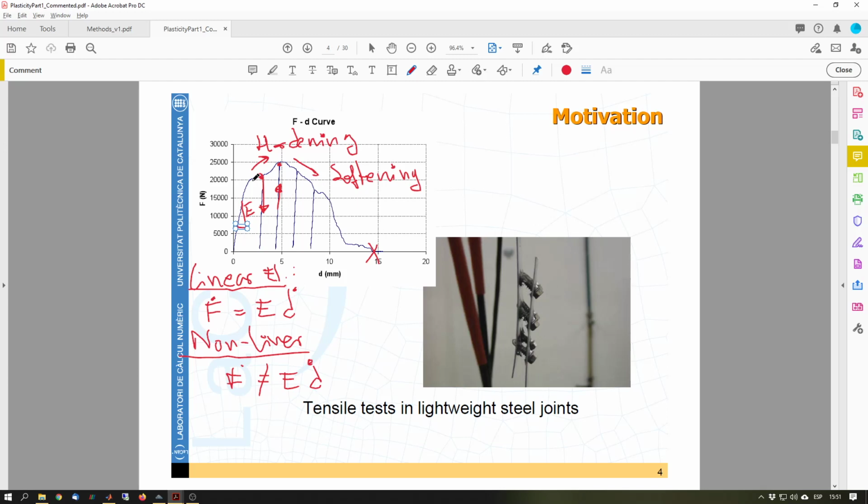So we are going to focus not on this whole history of loading and displacement, but on something more simplified, something like that. We are going to work on a simplified model to reproduce material behaviors like that, but not with the screws, rather in our continuum approach. That's what we know how to model so far, with elasticity and phase field models. So we're going to include, first of all, the idea that there is a maximum load beyond which things become nonlinear, and the idea that if I unload, I go through a different branch.